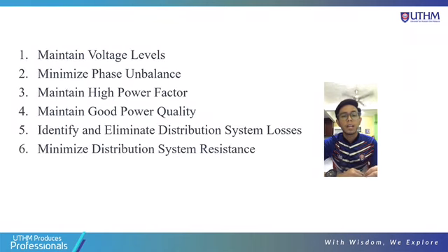First, maintain voltage level. Second, minimize phase unbalance. Third, maintain high power factor. Fourth, maintain good power quality. Fifth, identify and eliminate distribution system losses. And the last one, minimize distribution system resistance.